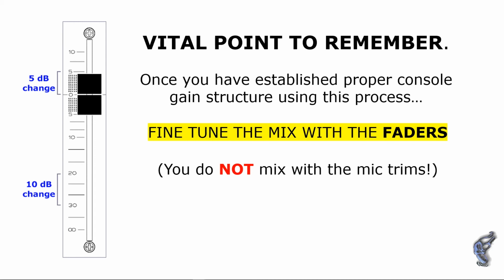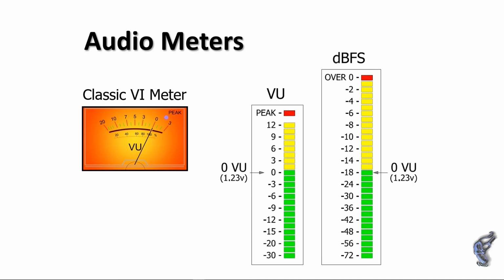Your goal, the condition you want to see, is whenever the music team is playing a big, strong, powerful song, you should regularly see the main output meters of the console cresting around 0 VU. It's okay for them to spill into the area above 0 VU and to ride below that point, but fairly regularly we want to see the music peaks at around 0 VU. Once the gain structure is set, we can make adjustments as needed to refine the sound character of those individual channels.